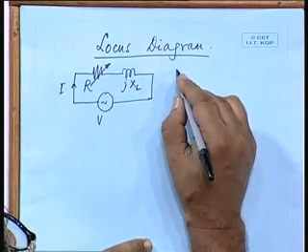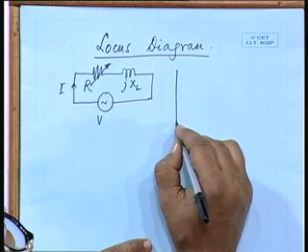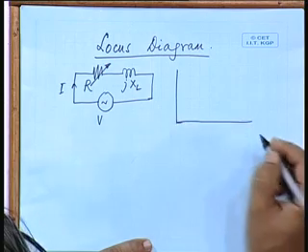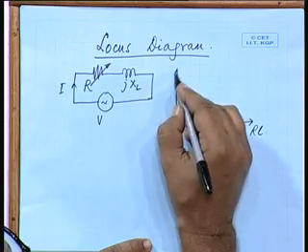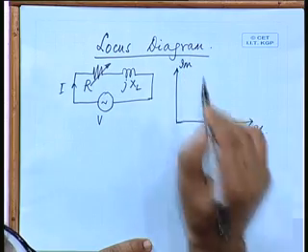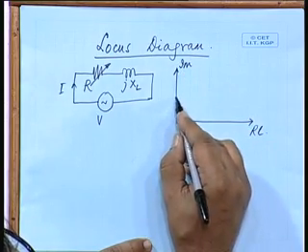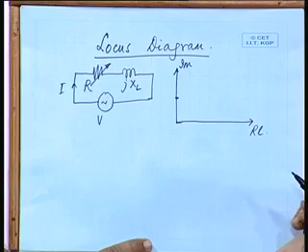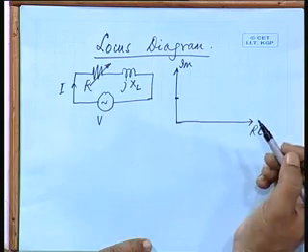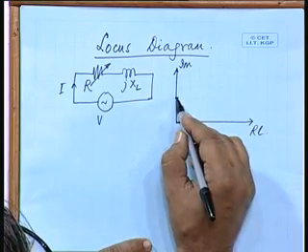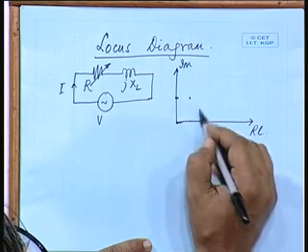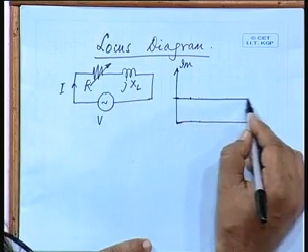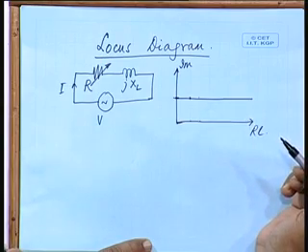So, if we see the impedance diagram, suppose this is the real part, this is the imaginary part, then it is JXL which is fixed and we are taking different values of R. So, R plus JXL will be say R1 plus JXL, R2 plus JXL. So, the impedance varies along this line, is it not?